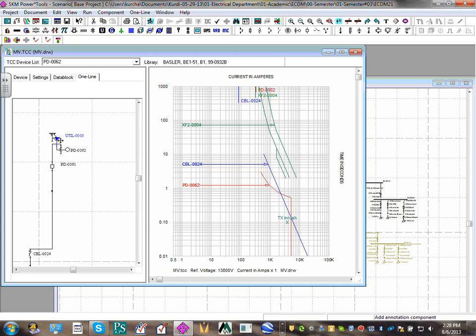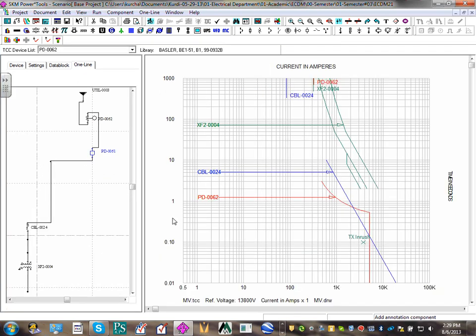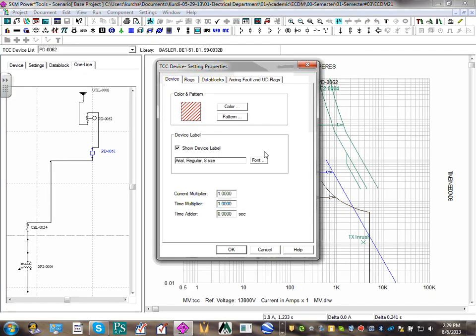When it comes to the medium voltage, guys, circuit breakers are dumb. They're muscles only. They don't do much, and you need to stick a relay. So you can see the relay's coming here to trip the circuit breaker. So here's my relay.